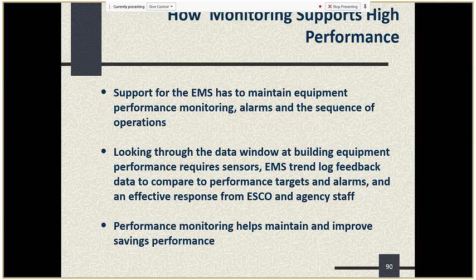Having the data window of an EMS system to look at your building equipment gives you a lot of advantages, but it's dependent upon having quality sensors, making sure that those sensors are cleaned and inspected, and that the equipment they're controlling is functional, for example, dampers or a VAV box. All these things are linked together, and you have to maintain the integration of the control sequence of operations to make sure it's actually happening, or you start seeing erosion or degradation of savings.